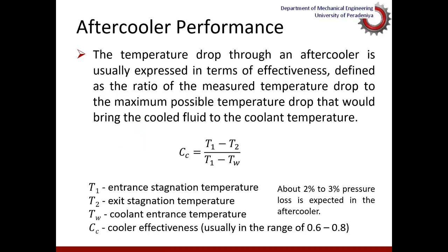And the performance of the aftercooler or the intercooler is also directly related to the temperature drop or temperature reduction, and it is defined in the form of cooler effectiveness, which is defined as the ratio of the measured temperature drop to the maximum possible temperature drop that would bring the cooled fluid to the coolant temperature.